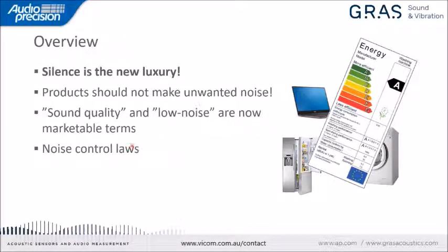But now it's also time to talk about noise control laws, noise control regulations. And I can say they are particularly important, at least in Europe where I live. So for example, consumer electronics devices such as computers have to go through noise measurement tests for certification. An example of this is the new machinery directive 2006/42/EC from the European Union. This directive has a section about noise control saying that the noise of the device should be assessed in a way that is comparable with devices of the same category.